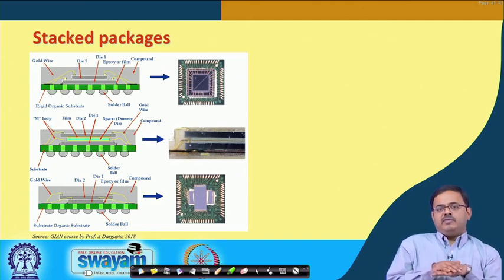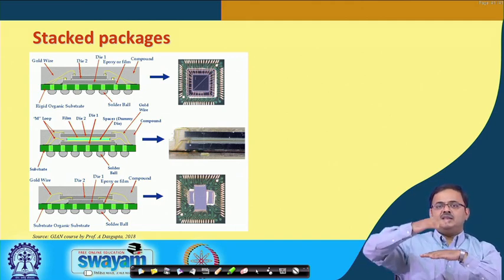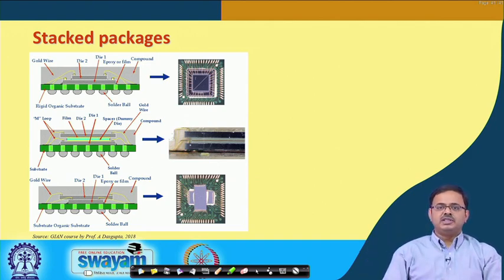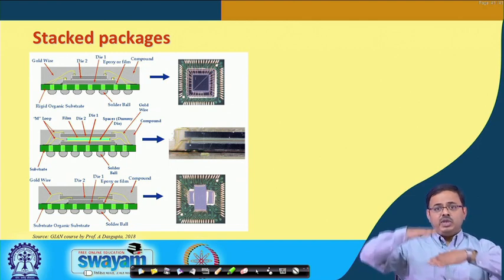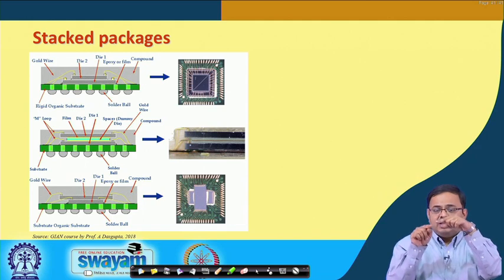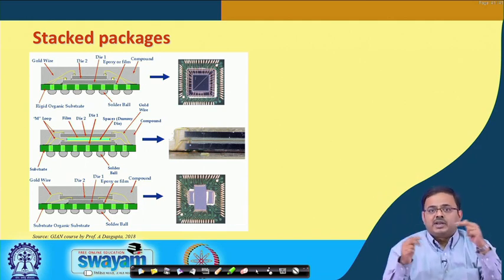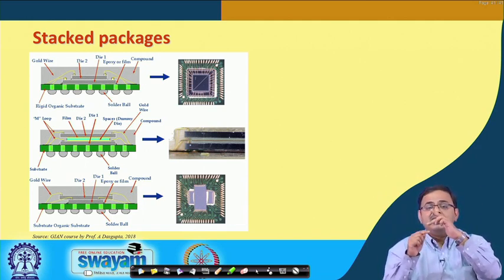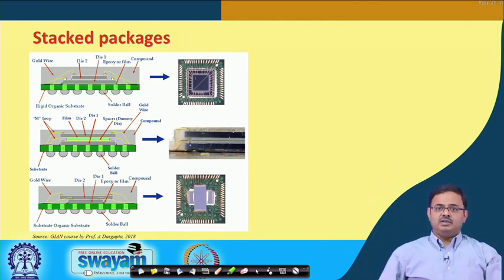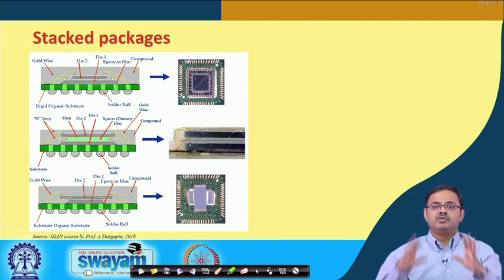Now, let us say you have an n layered stacking of such dies, one on top of each other. An electrical engineer would say that you just stack them identically on top of each other, because then if you look at two cores, for example, they will have the lowest electrical distance in between them; they will just align one on top of each other. Electrical performance would be wonderful.